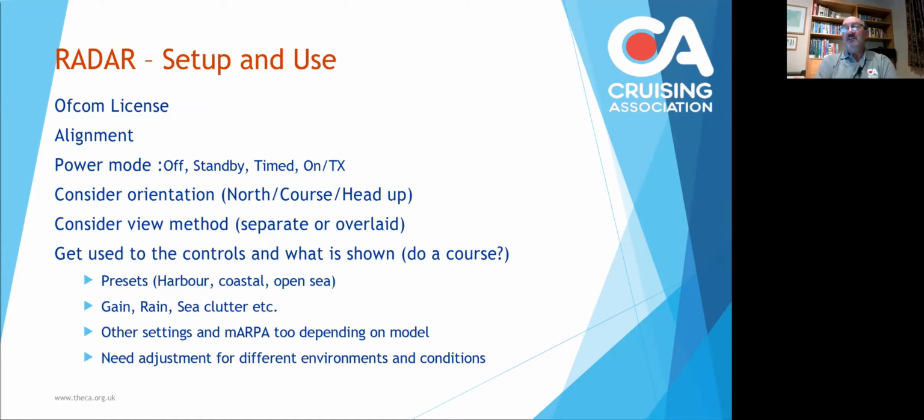Now, you've also got to consider the orientation of which way round the radar information is presented to you. I have to say my personal favourite is north up. So that means that I'm looking at the radar in the same way that I would be looking at my plotter screen. But equally, you could do course up, which is a very good way of looking at it, because then from a logical point of view, going upwards on the screen towards the top is as if going directly in front of your boat's heading.